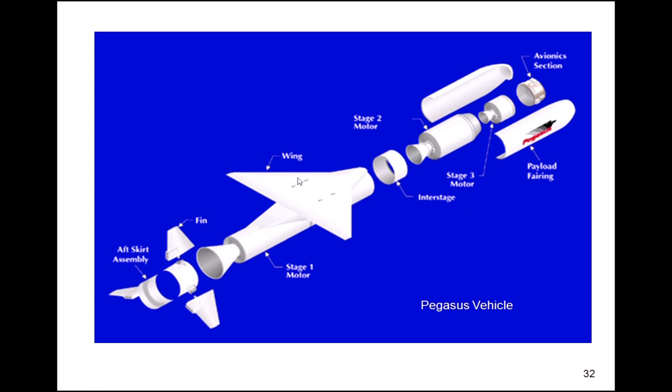Now, the L-1011 initially is mounted to Pegasus, or perhaps I should say vice versa, through 4 hook fittings. The hooks are in the L-1011, and they come down and they tie into these bathtub fittings. So during stage 1 burn, when Pegasus is still in the sensible atmosphere, this wing is used to provide aerodynamic lift.